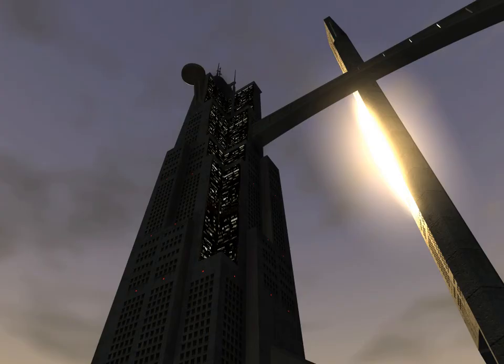So the last topic we'll cover with direct lighting is that of thresholded shader glow. And again, this is more of a shader attribute, but it's a lighting related issue because it provides a sense of a lighting bloom. Obviously this example is a little over the top, but it does show the nice behavior that it can have. Again, specular blooms like this are often best done in compositing. Doing them in Maya makes some sense oftentimes because of matting issues, but in general can also be done as a glow pass, and that can be probably the best route to accommodate these.